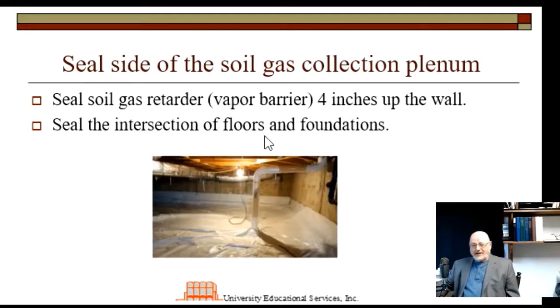And I should like to point out that the concrete itself is not impervious to radon. There's a thing called the diffusion coefficient. It tells you effectively how easy it is for gases to penetrate different materials. And there's a diffusion coefficient for radon in air. How easy is it for the radon to diffuse through the air? And then there's a diffusion coefficient for radon through concrete.